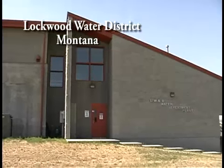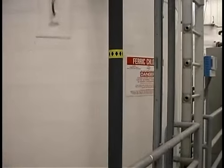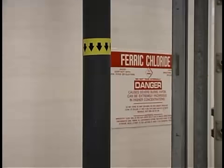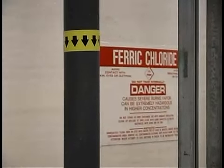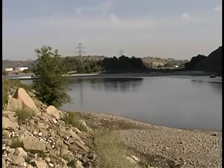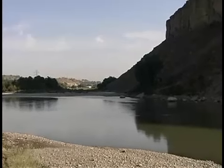With the revised arsenic MCL looming in the future, the city of Billings began experimenting with coagulants other than alum to increase arsenic removal. Billings converted to ferric chloride as a coagulant. Arsenic in the Yellowstone River, because it's a surface water source, is arsenic-5. Arsenic-5 is relatively easy to remove.